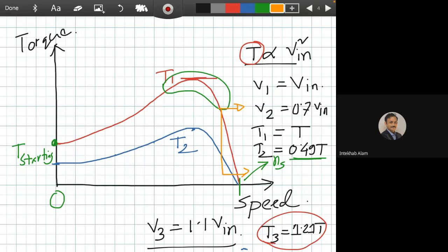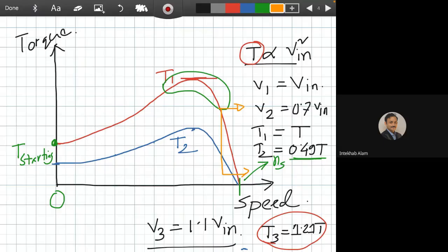Have you ever heard that point? So this is the starting point, and here the rotor speed is speeding up, and here it achieves the maximum torque, and after this part, this is the stalling part, and we do not use this stalling part.